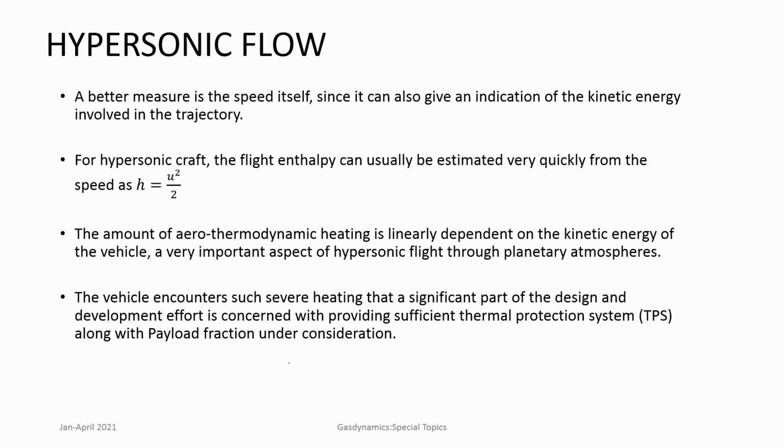Mach number in general, if you look, it actually relates how the kinetic energy of the flow is related to the internal energy of the flow itself. So, as Mach numbers increase very quickly, we find that the kinetic energy contained in the flow can be as high as the enthalpy of the flow itself.